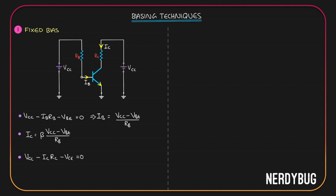From this, I can write an expression for VCE. It is VCC minus ICRC. But IC is beta times VCC minus VBE by RB. So we can write VCE is VCC minus beta times VCC minus VBE by RB multiplied by RC.